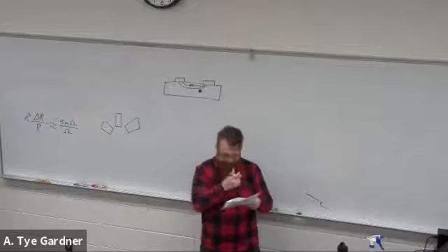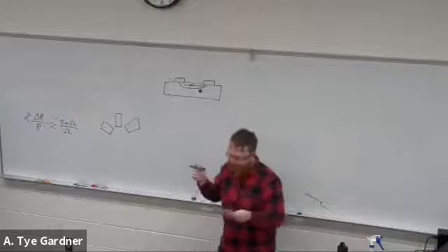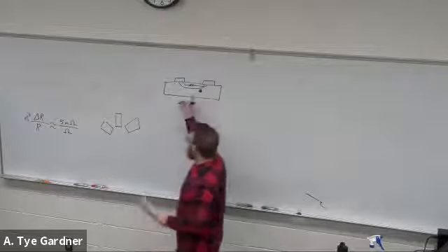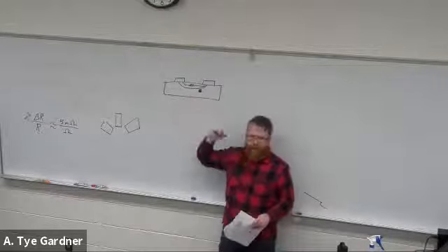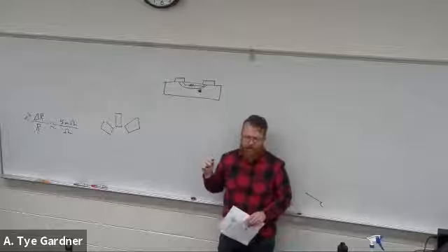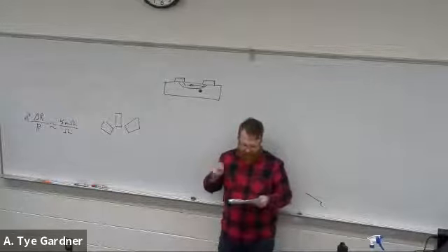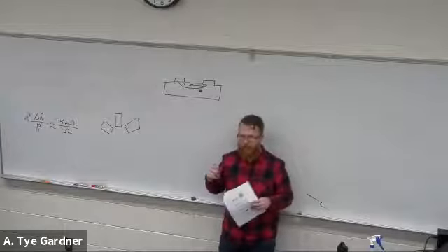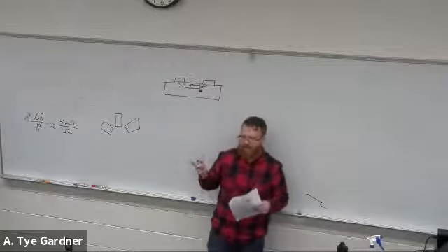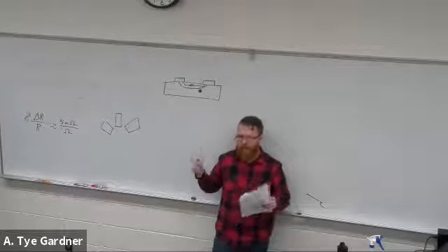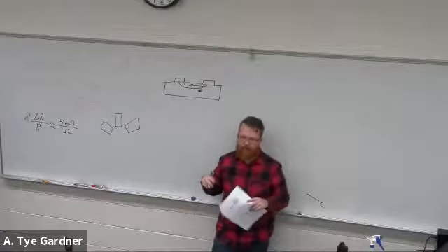Okay. So the final issue that you have with silicon is that its transfer function is nonlinear. So unless you're having very small deltas, you can run into a problem. Generally the data sheets for these ones are better, but you still have to be very careful with your transfer function and your calibration.